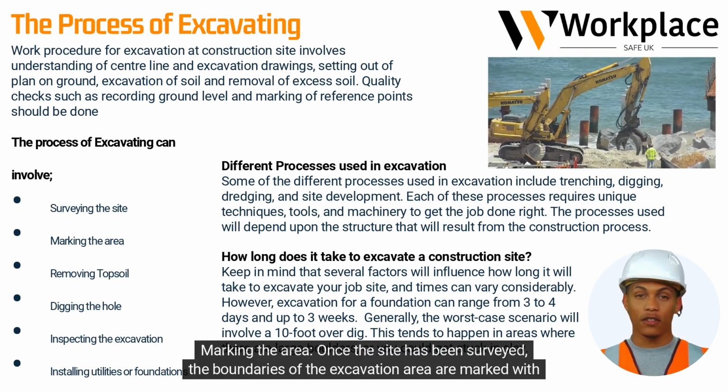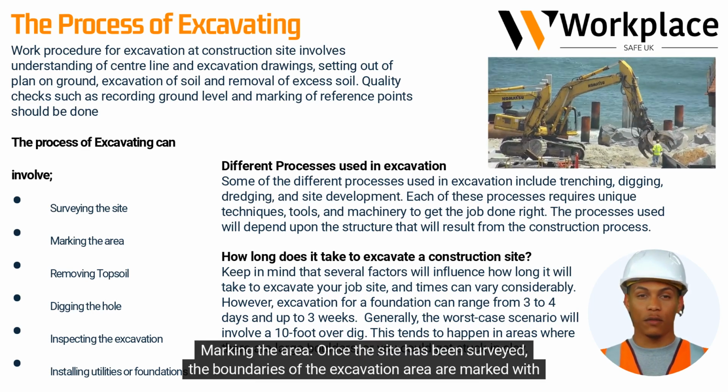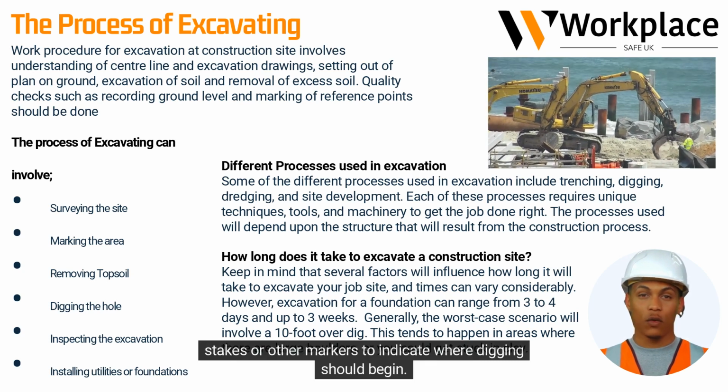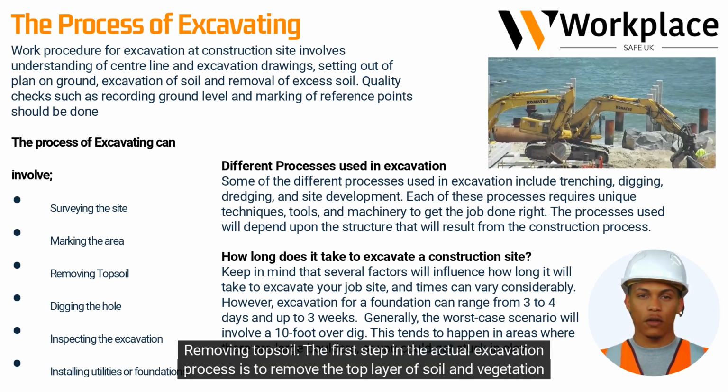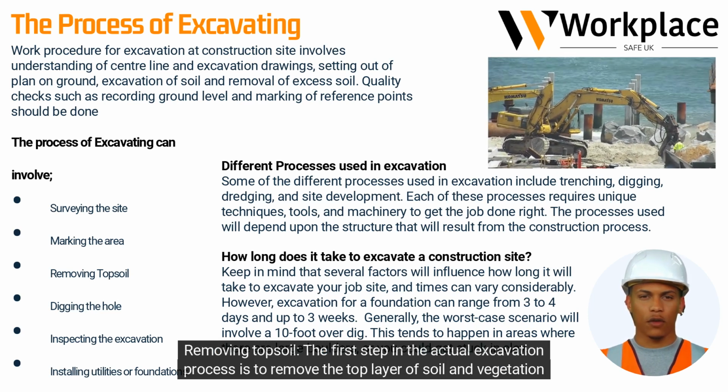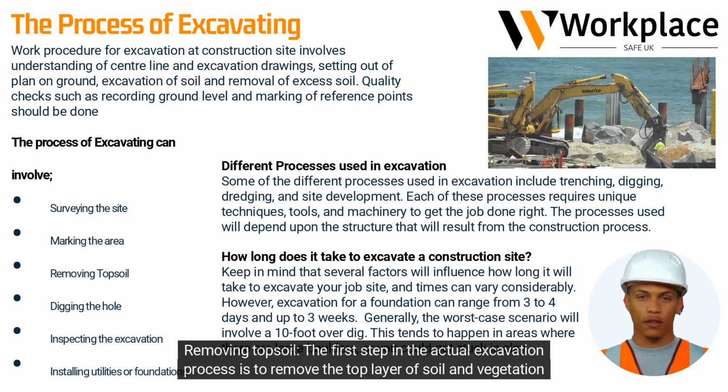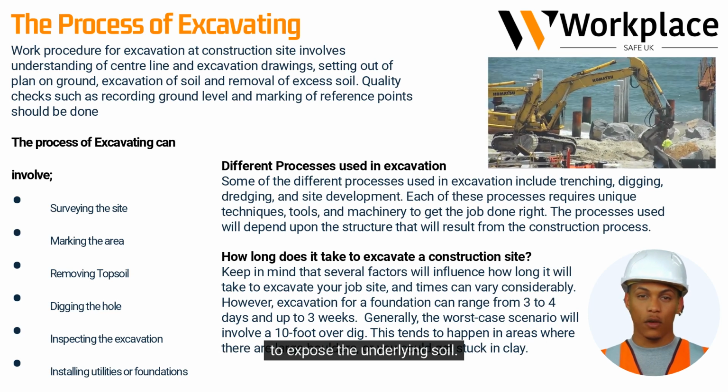Marking the area. Once the site has been surveyed, the boundaries of the excavation area are marked with stakes or other markers to indicate where digging should begin. Removing topsoil. The first step in the actual excavation process is to remove the top layer of soil and vegetation to expose the underlying soil.